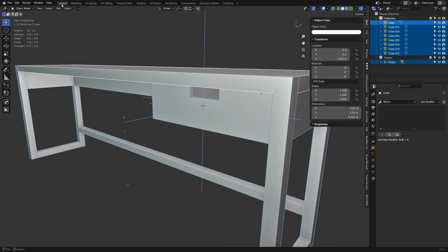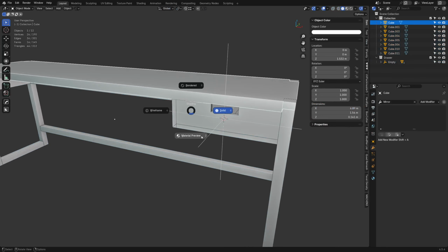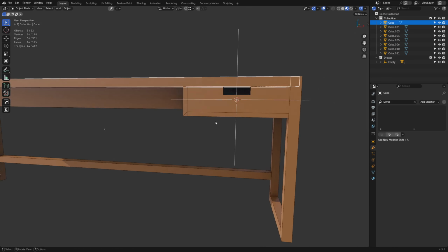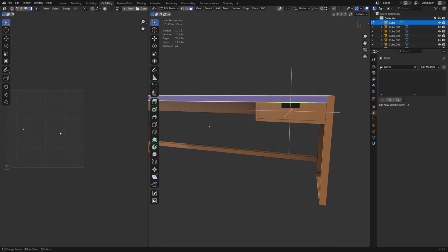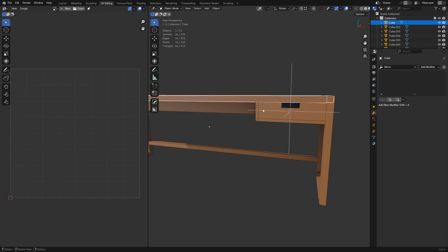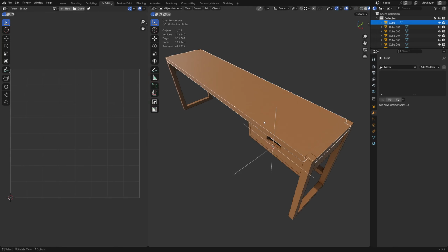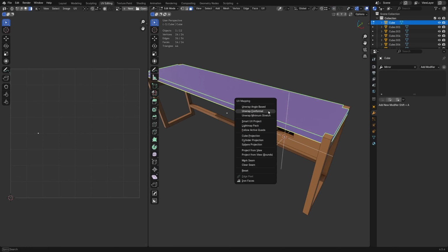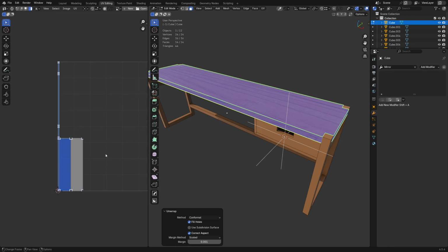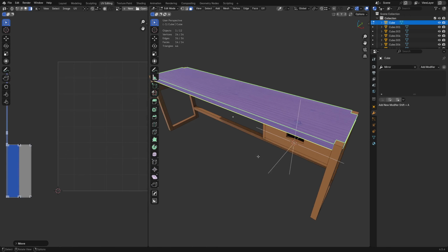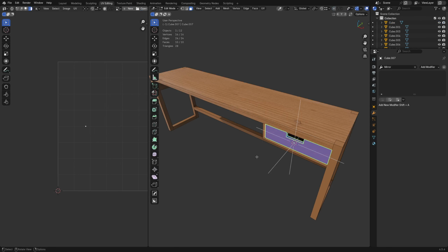And when we go into layout here, and we're in material preview, we need to just keep working with full screen. And maybe we'll hide this for now because we're not using it. But this is kind of the fun thing about this. Like when you set them all to 0, it flushes out the whole texture basically. So anytime you want to make something and unwrap it correctly, like unwrap conformal, you want to check that it's working. You know it's unwrapped now. You can move it out of the UV space. You're done. Okay, so the next one you do, unwrap conformal, make your adjustments.